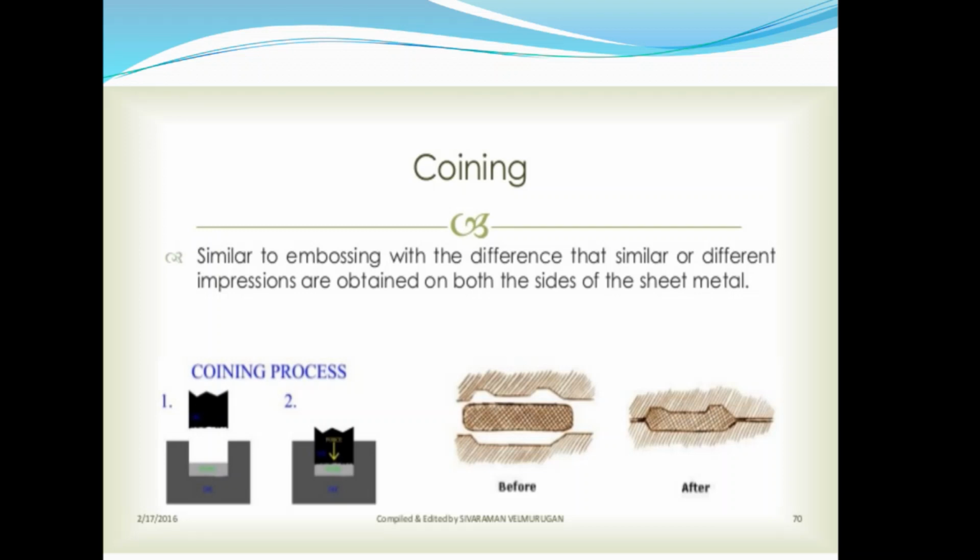Next, coining is nothing but the same as the embossing process. In embossing, we give the material a certain shape. So we put it between two partial dies, that means two half dies. We place the workpiece there and then press it, so the workpiece is molded to a certain shape. That is the coining process.